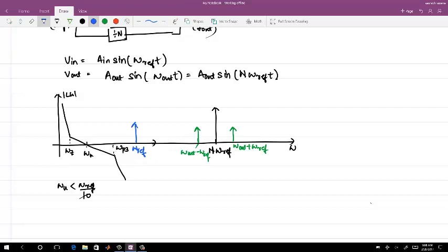Now the closed loop response of the PLL from phi in to phi out, let me plot it here. It shows a minus 3 dB at omega u, and this value is 20 log of N. This is the closed loop response phi out by phi in for the phase.